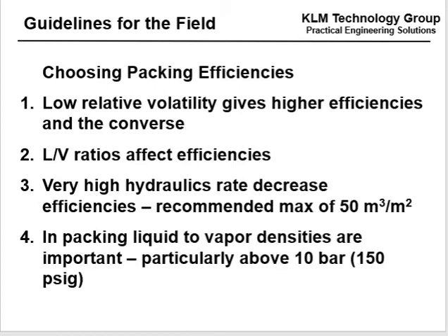Packing, the same effect. If the relative volatilities are close, the boiling points are close together, you get higher efficiencies. Liquid vapor ratios affect efficiencies. Very high hydraulic rates decrease efficiencies in packing. So there's a recommended maximum of 50 meters cubed per meter squared.